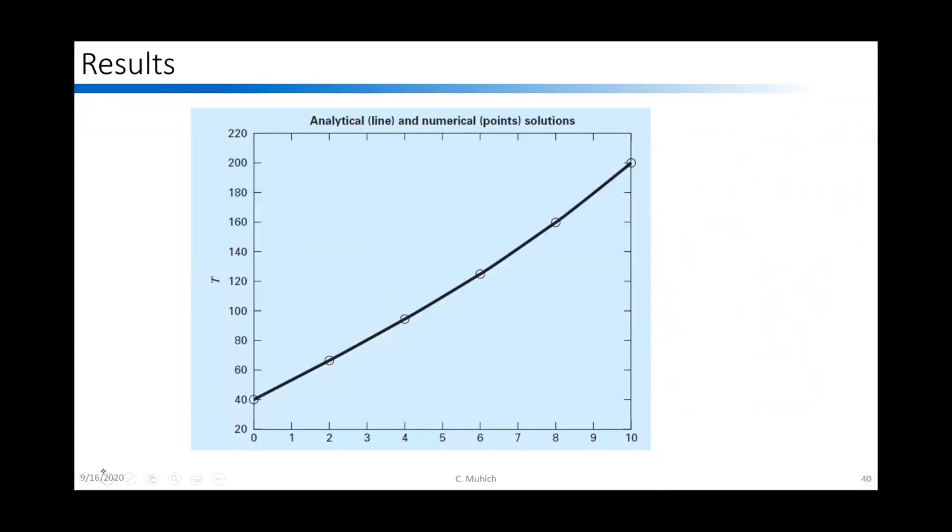If you go in and do that, we can calculate at each of these points T1, T2, T3, T4, and then we already had T5 and T0. Just as a reference, I put in the analytical solution, and we can see that this numerical approach via algebraic equations gives us quite good answers in comparison to that purely analytical method.